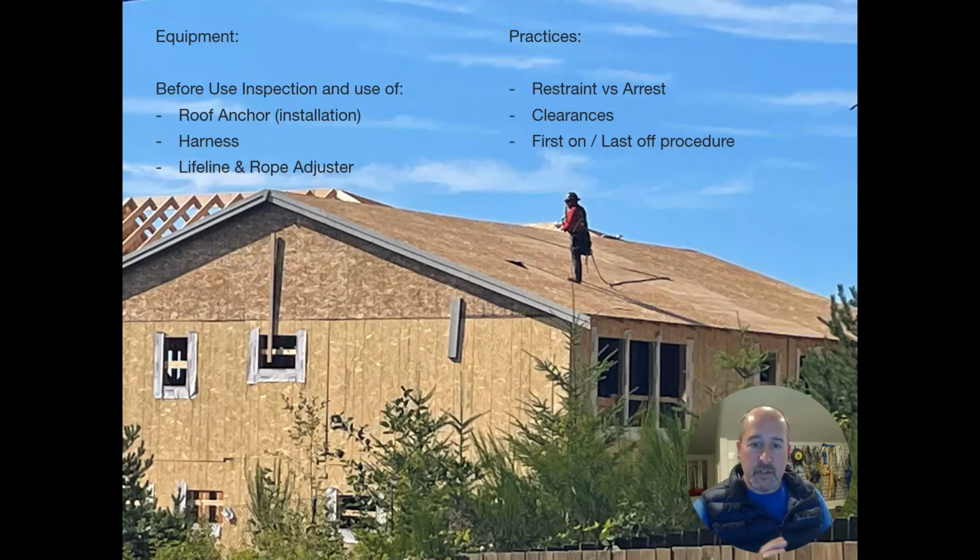All too often, you'll see pictures of this and somebody goes, oh, you nail it down, and then they move on, and they don't understand that, especially with roofing anchors, going through the sheeting and connecting to the truss member underneath it, that's the only way you get your strength out of these anchors, and using all of the fasteners required. So by conducting an experiential exercise, not only does the person understand how to do it correctly, but they just as importantly understand when something isn't correct.